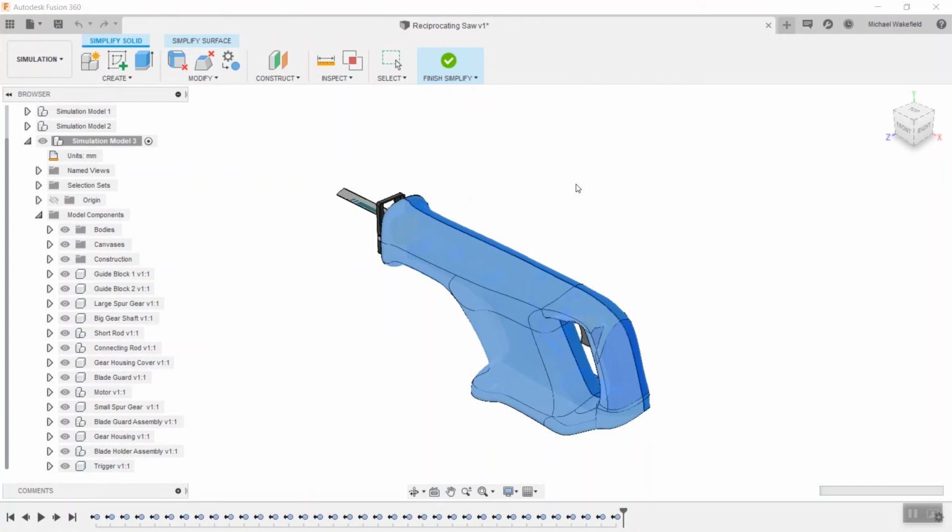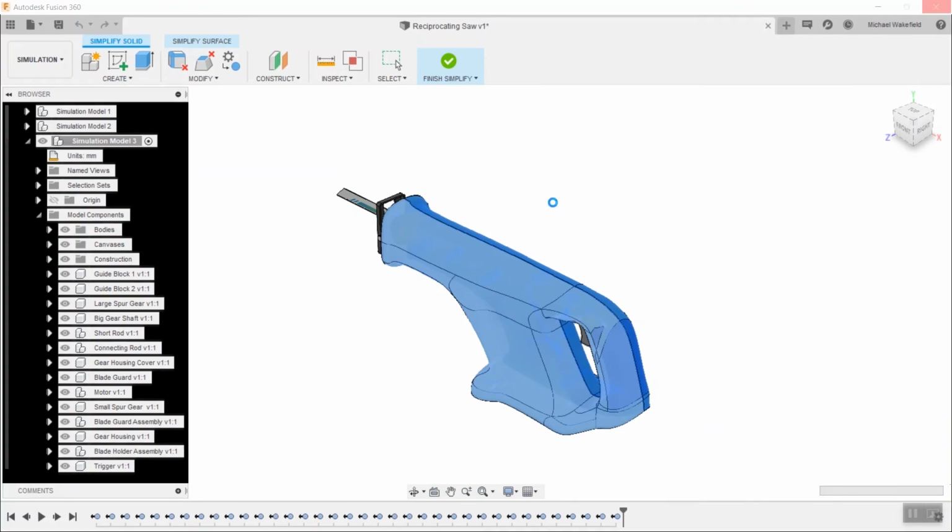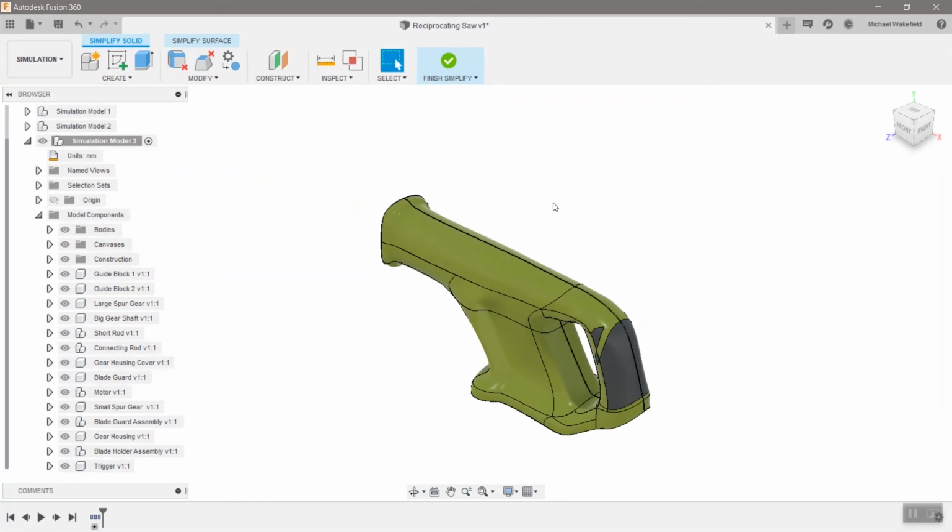But, you know, by selecting by size, I could then right mouse button, and I use the command remove all but selected. So you can see down there on the timeline, a bunch of those parts that I had selected by size are now being removed. It's quite a number of them, so it does take a little while to do. And usually, if you do this well, there'll only be a few other parts that you have to go get. So in this case, I went back and turned on all those parts to see what I had left.